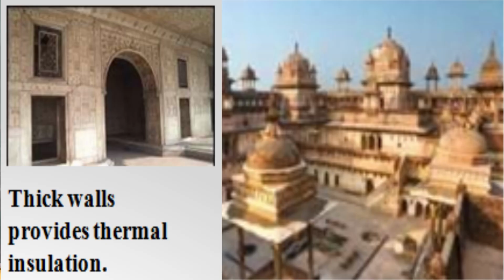okay, where the thick walls provide the passive insulation and the domed or curved roofs as well as the curved shaping can provide shade to a particular area, and the arched ceilings are helping to cool the internal space of the roofs. So which is providing the alternate heating and cooling effect for a particular building in order to enhance the cooling effect.